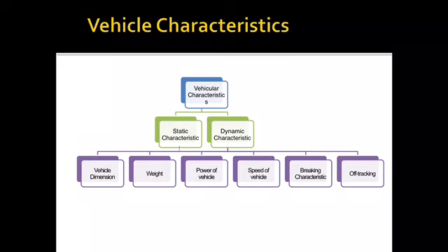That will affect the visibility distance, the distance visible to the driver ahead of him. Also, the height at which you have provided the headlights is particularly important during the night time, when you travel in valley curves or on gradients, or in hill stations. The height at which you have fixed the headlight decides the visibility during the night time under the headlights.